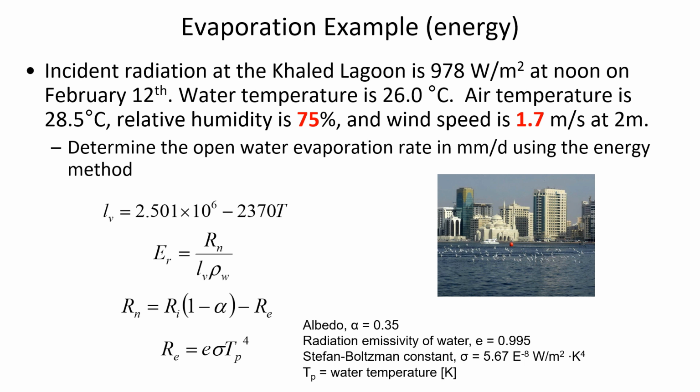So remember, long wave radiation, let me explain it this way. Have you ever walked in front of a brick wall after sundown and you can still feel the heat coming off of it? You can feel it even if you are 4 or 5 feet away from the brick wall. It's not convection that you're feeling. You're not feeling warm air.